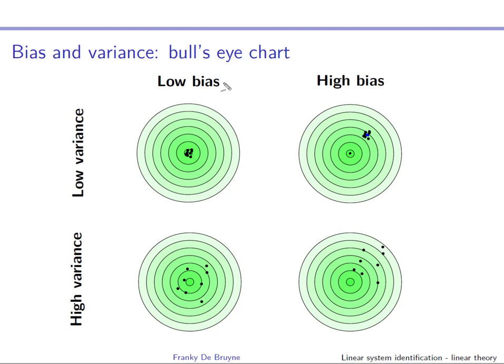We want, of course, a low bias, but we want also a low variance. The variance is the variability around the average measurement. You can see here that the average measurement produces a correct measurement, but since there is so much variability, we do not like this sensor because the variance is too high. So the ideal sensor has low variance, low bias. Note that you can correct the bias by calibrating the measurement. It's much more difficult to do something about the variance.